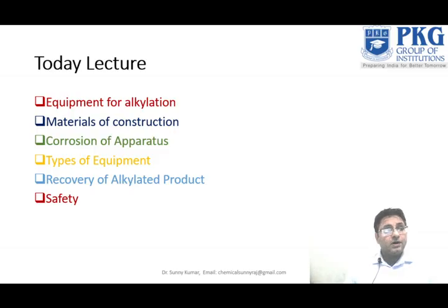We have to consider the different thicknesses of the material, and what type of catalyst we are using during the reactions, which is also very important, and what type of lining we are using for coating the surface of the equipment. Monel-type or enamel-type coating we generally use, which is a glass-based or mixed-metal-based coating.